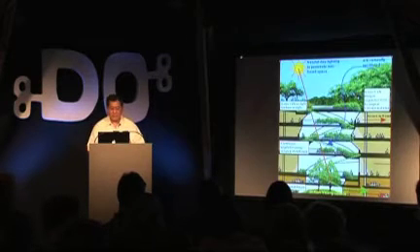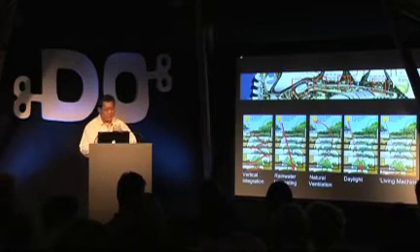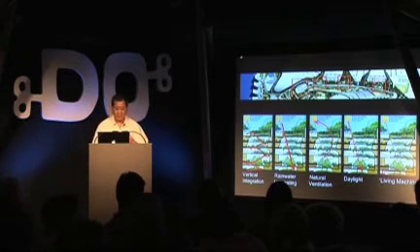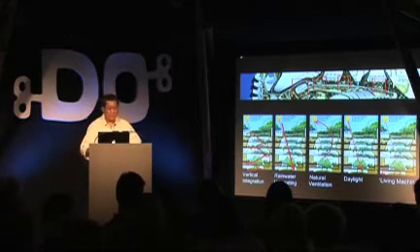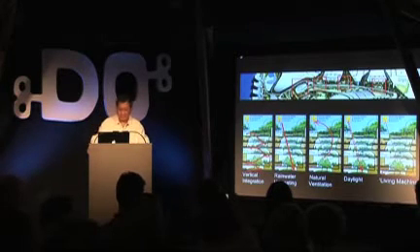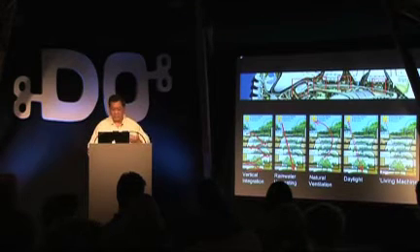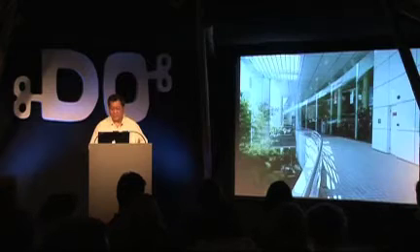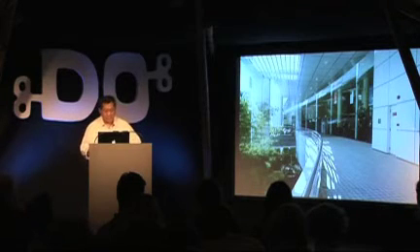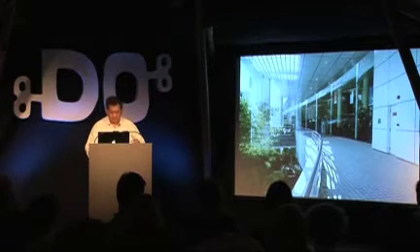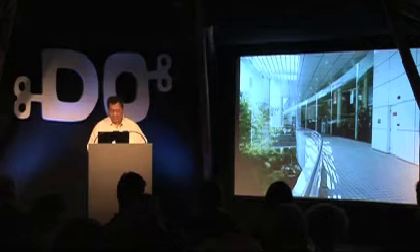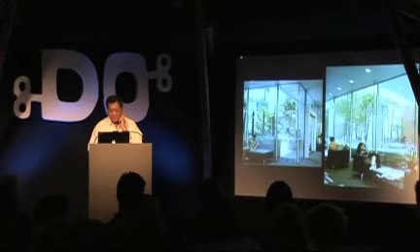And the eco cells do a number of things. They bring vegetation into the inner parts of the building, provide opportunities for rainwater harvesting, bring natural ventilation, bring daylight, and obviously it's where the water retention pond could be, or where you could have a living machine for sewage. Here's an example of what an eco cell could look like. This is the project we did in Singapore, the National Library.